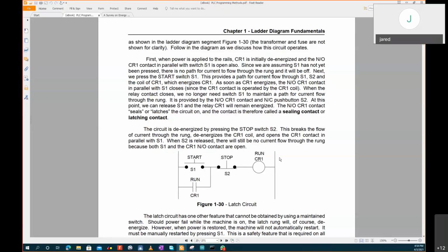You can do it mechanically. Itself has these logics which you're going to do programming, and you'll understand how they work. But this is the representation of the circuit. So this is the stop. This is like an emergency stop. We said an emergency stop is a contact which is normally closed. You see, it's already normally closed, but this one is normally open.